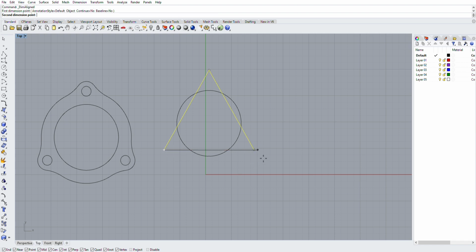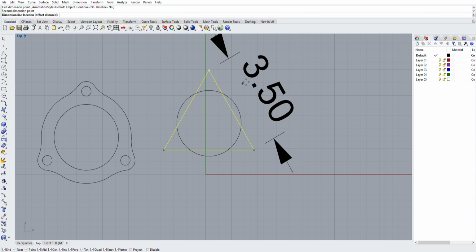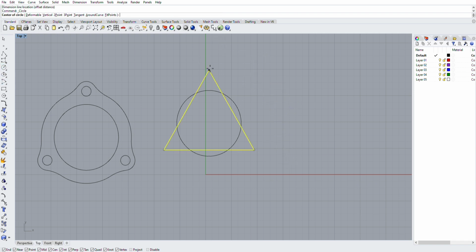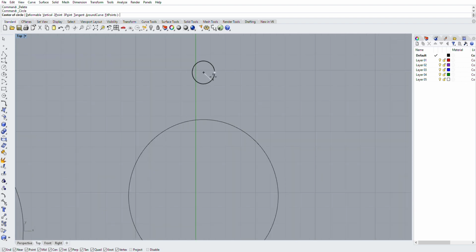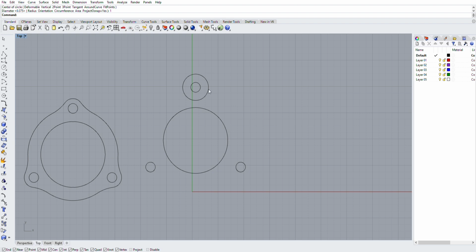Now, all we have to do is grab our circle tool, and you can see all 3 sides the same. Our circle tool, and put our 3/8 bolt holes here. I mean, maybe it's a 1/2 inch bolt hole. This is all something you can lay out. It's just a couple of keystrokes away. But now, instead of using the polar array, we've used this tool here because we had our dimension from bolt hole to bolt hole.